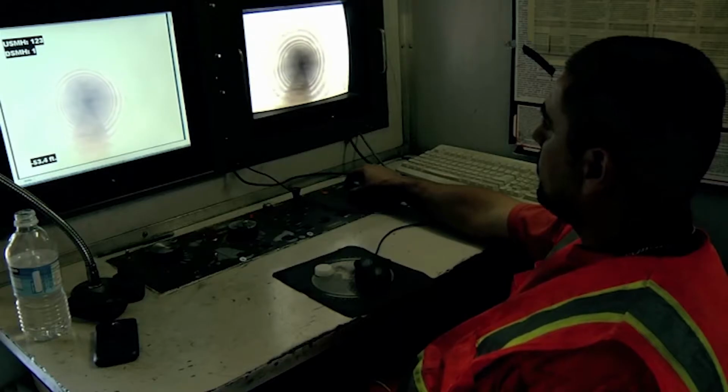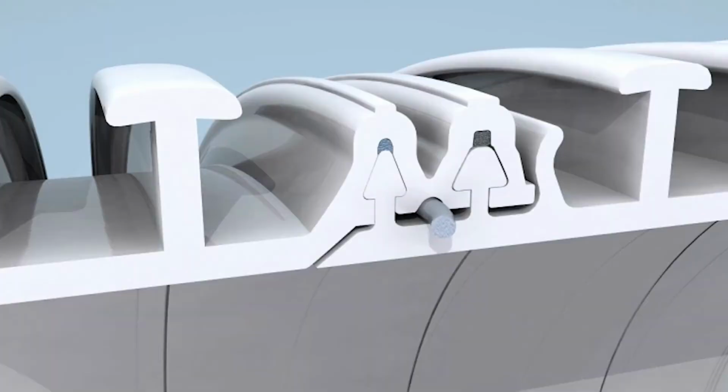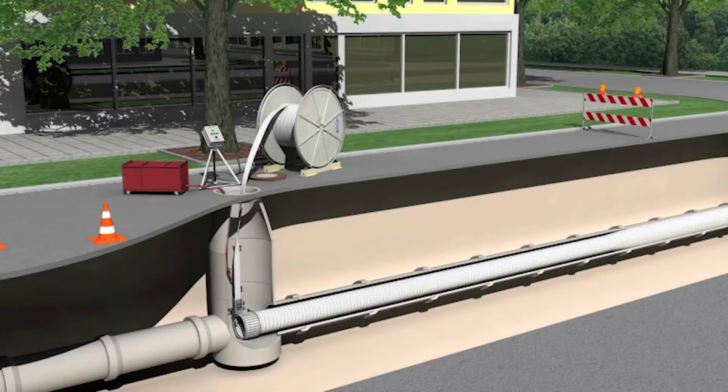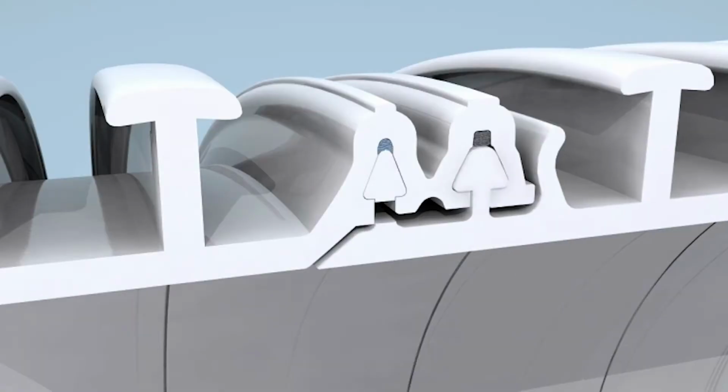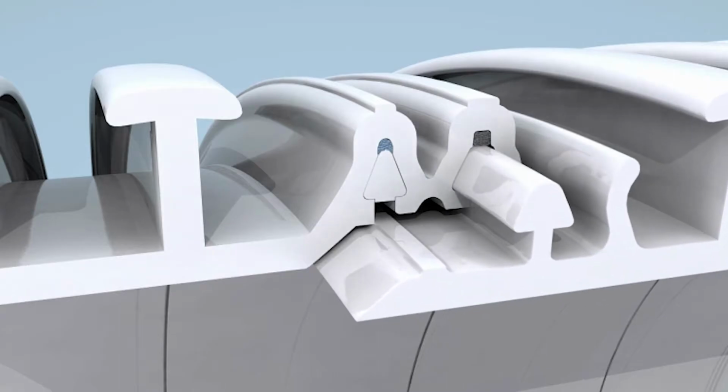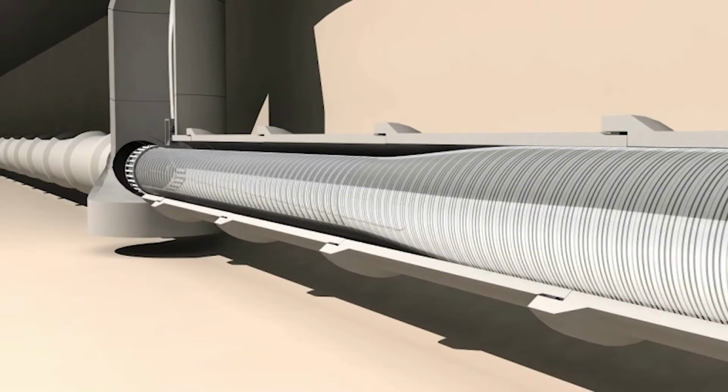Winding is stopped when the wound pipe reaches the next access chamber. The end of the SPR-EX liner is then torsionally restrained. Expansion of the liner commences by pulling the cutting wire, severing the secondary lock. As the wire is progressively removed, more profile is wound into the liner. The lubricating sealant in the primary lock allows adjacent profile wraps to slide relative to each other.